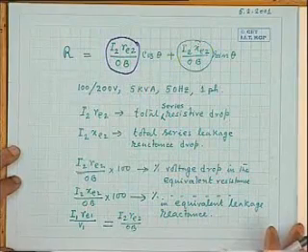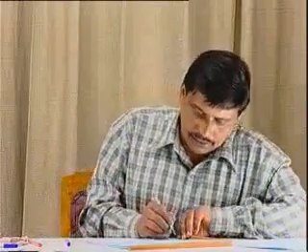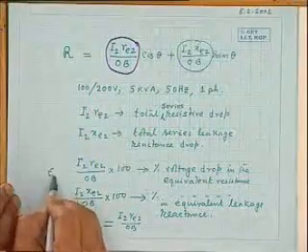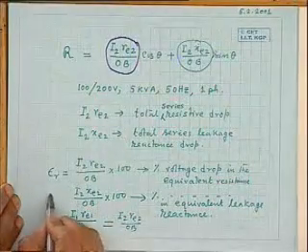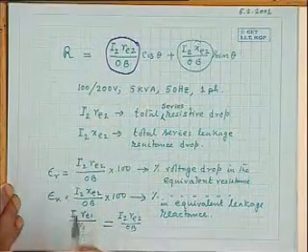So sometimes instead of telling the resistance and leakage reactance values in ohms and referring to a particular side, the per unit values will be only specified. Obviously, you can calculate the exact value of the resistance if you wish with respect to a particular side, if you know this relationship with this physical idea. And these are denoted by this letter, epsilon r. And this is epsilon x.